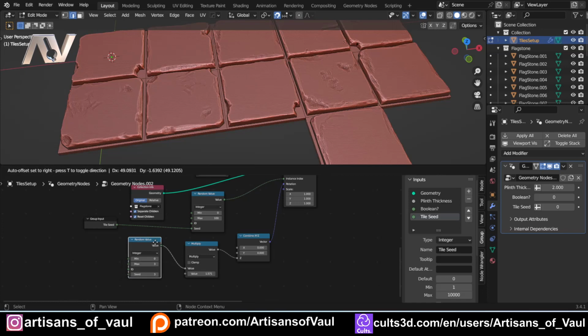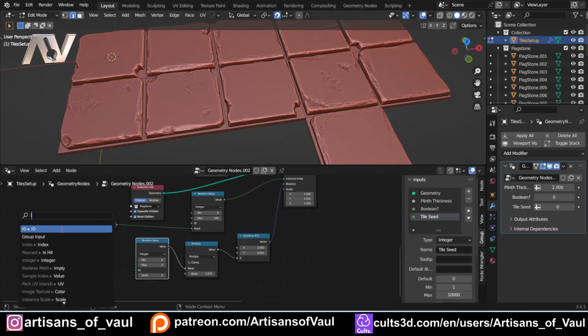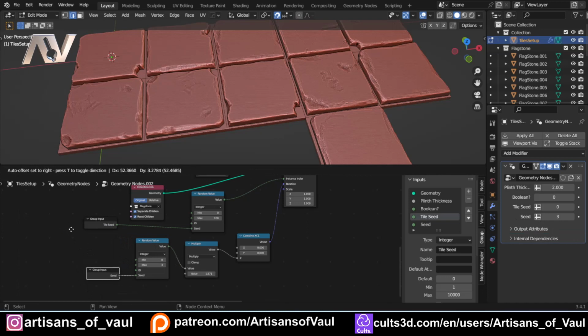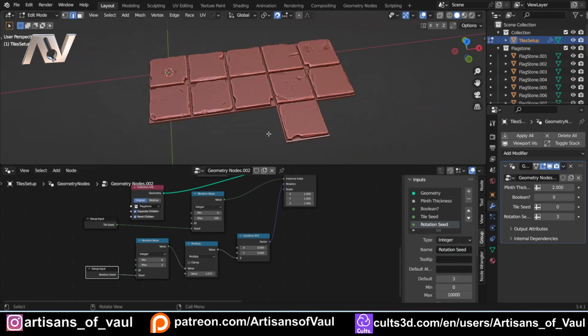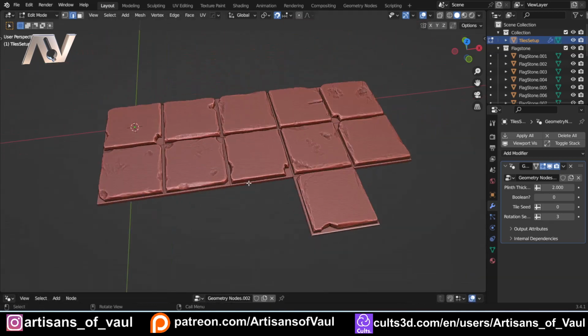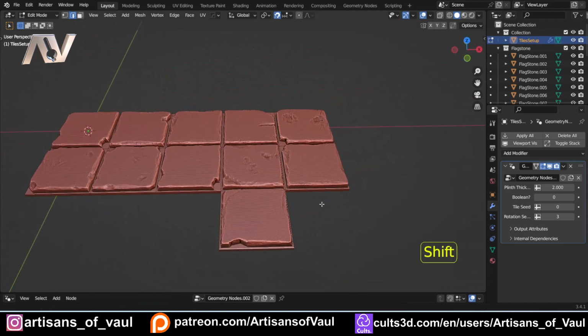And then we want to change our rotational value seed. So again, I'm going to do that as another input. So group input there, and again that's called seed. That's why it's important that we rename this, and we'll call this rotation seed. And again, default of 0, minimum of 0, maximum of, well, we'll leave it at 10,000. So now at this point we don't need that. Everything is controllable by here.